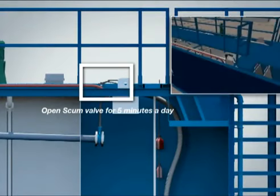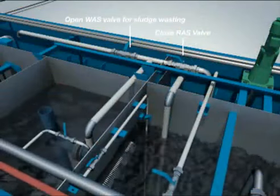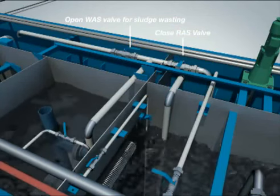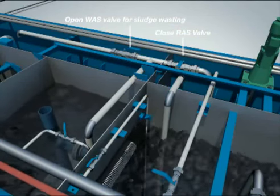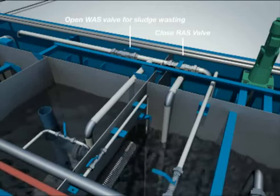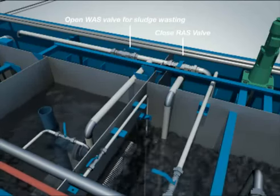Open the scum valve for 5 minutes a day or until the top of the clarifier is clear, so that the scum floating on the clarifier will be recycled back to the EQ tank. Close the RAS valve and open the WAS valve for 15 minutes as often as advised. The frequency of this operation may vary for each unit and will be advised by the visiting process engineer during the weekly site evaluation routine.